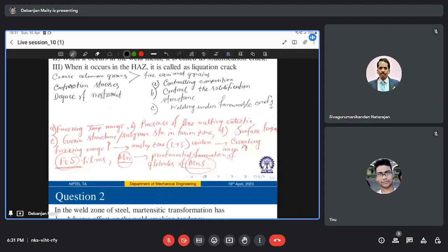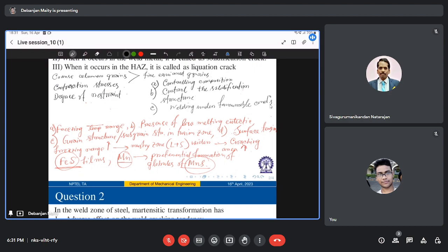So to effectively avoid or reduce solidification cracking in autogenous welding, basically what should we do? We should avoid base metal compositions that are prone to cracking, right? And when filler metals are used, the weld composition is essentially controlled by the composition of the base metal, the composition of the filler metal, and the dilution ratio, and to a lesser extent by the composition of the shielding flux or gas. The dilution ratio is basically the amount of base metal that is melted and dissolved relative to the total amount of metal in the fusion zone, right? This dilution ratio can vary significantly from one type of joint to another. So the joint design as well as the welding process and procedure should be carefully selected, right?